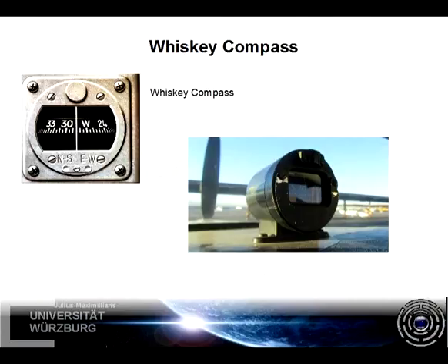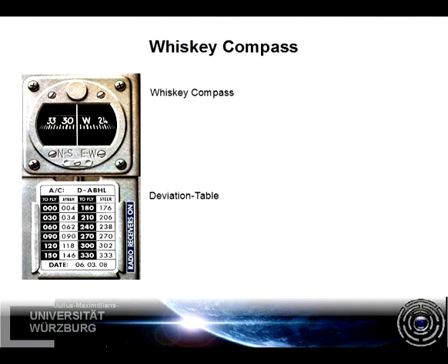As we mentioned before, the compass succumbs to electromagnetic interferences of the aircraft itself. Therefore, the compass does not indicate magnetic north directly. Since the interferences are assumed to be approximately constant, the deviation is measured by technical staff on a regular basis and presented to the pilots in the form of a deviation table that is placed right next to the compass. The table is very intuitive and advises the pilot in a "steer this to fly that" manner.